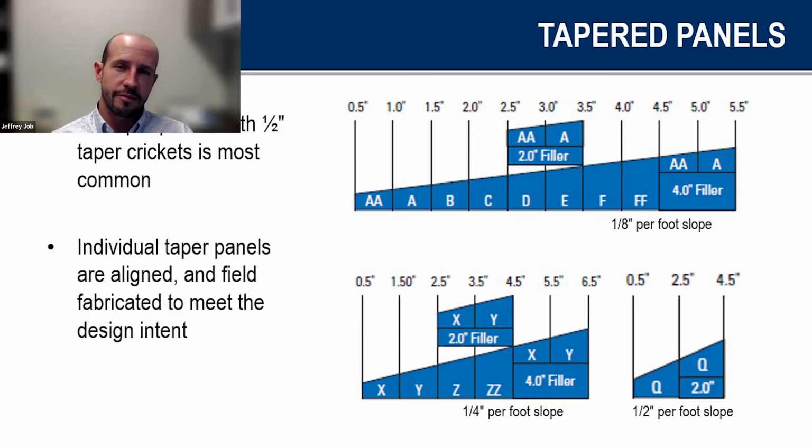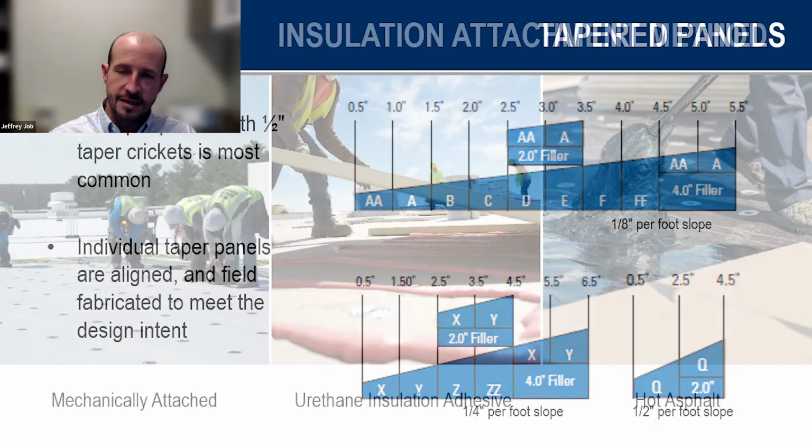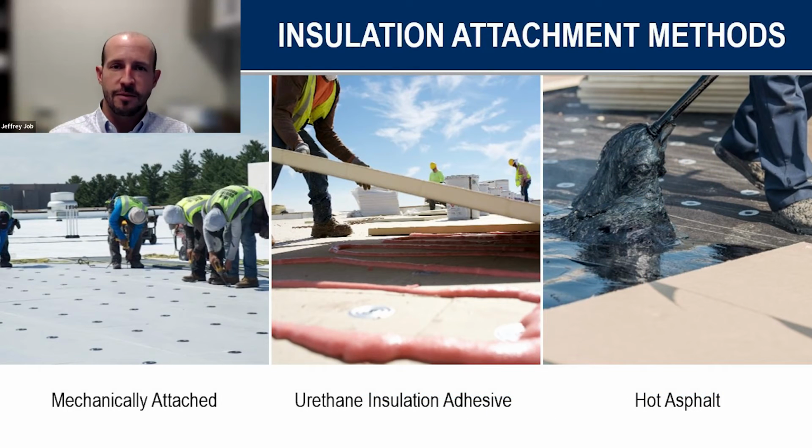or even what we might refer to as a hybrid, or again, a fasten one, adhere one, where we're going to fasten that first layer, then adhere that second layer to create that thermal break in the system, and then we're not spending the extra money to adhere the bottom layer as well. So you get a good middle ground, I would say, in high performance, in that we're not spending all that money on additional adhesive where we don't really need it, but we are including it where we do to help break those thermal connections. So that's a nice combination.